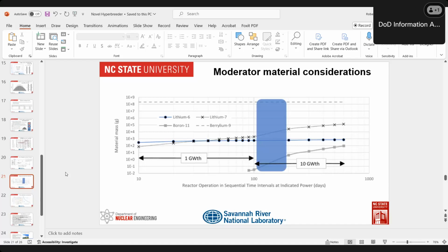Oh yeah. Nuclear batteries are going to be radioisotopic thermoelectric generators. So you're using the Seebeck effect. The easy way to think of it is like a thermocouple in reverse, kind of, so that by having two dissimilar metals that are welded together, if you have a temperature difference between the ends, it creates a potential difference, and you can use that to create an electric current.